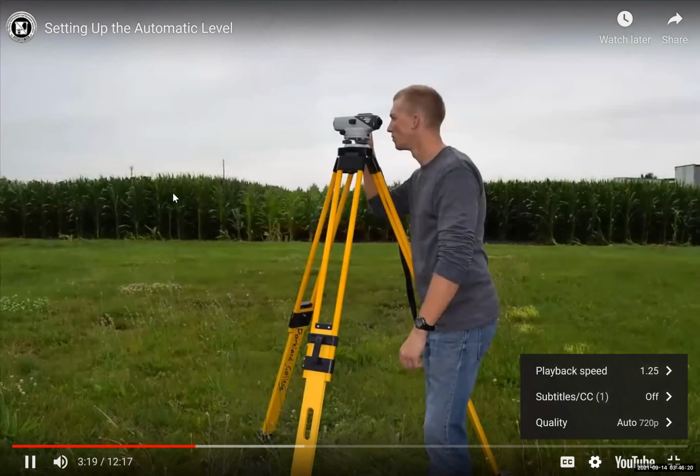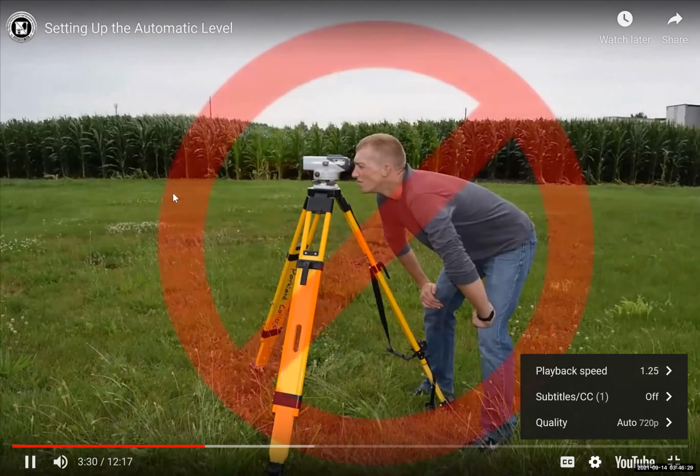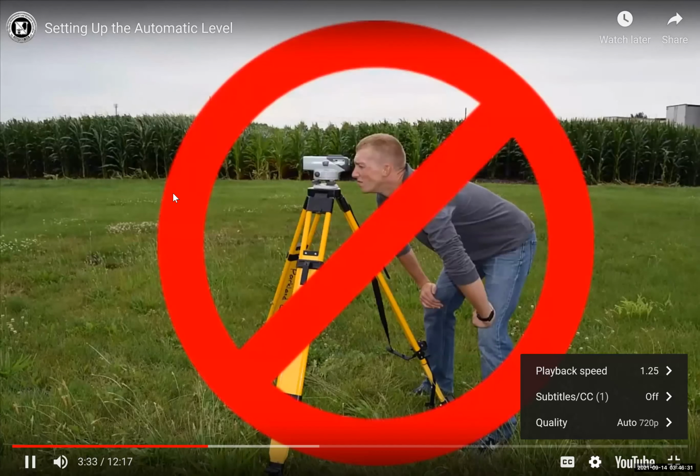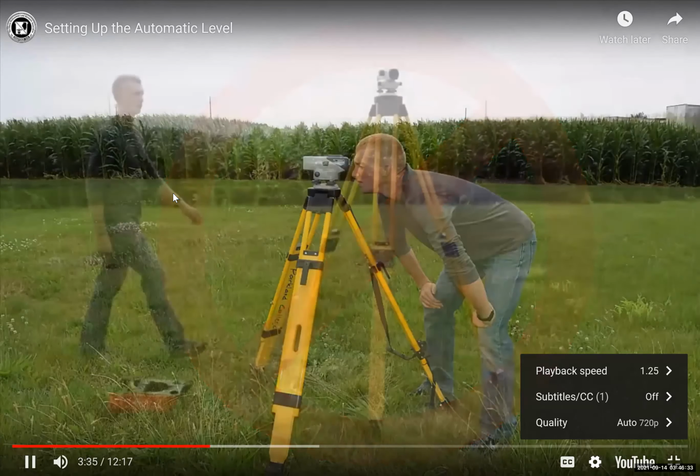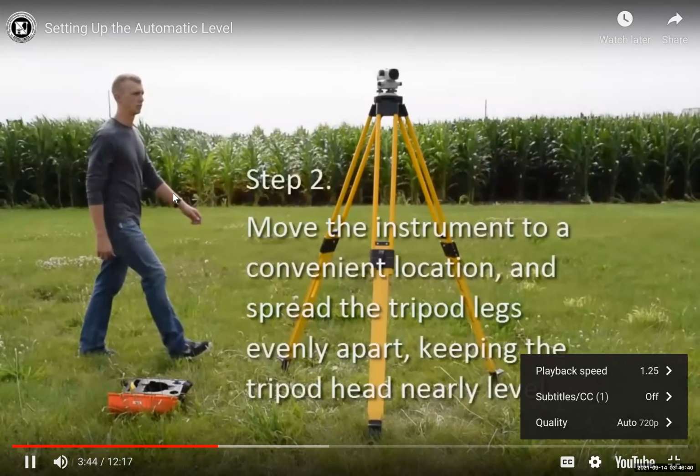When you extend the tripod legs, adjust them to ensure that you'll stand comfortably with the eyepiece at your standing eye level. You are more likely to misread the level rod when you're bent over like this. Next, move the instrument to a convenient location and spread the tripod legs evenly apart, keeping the tripod head nearly level.